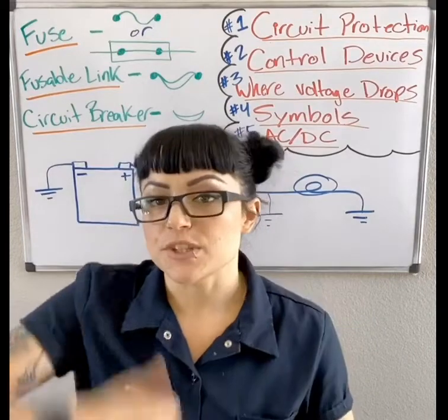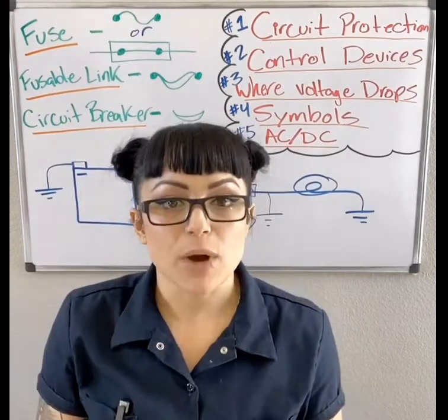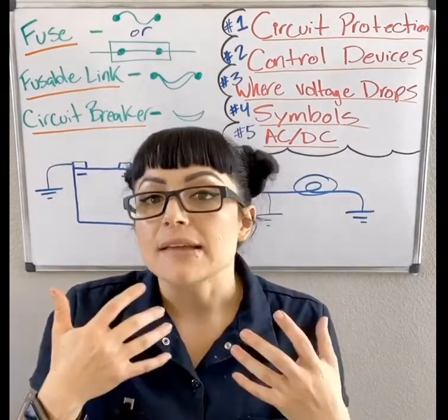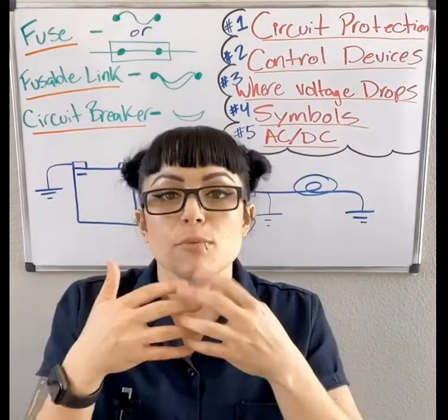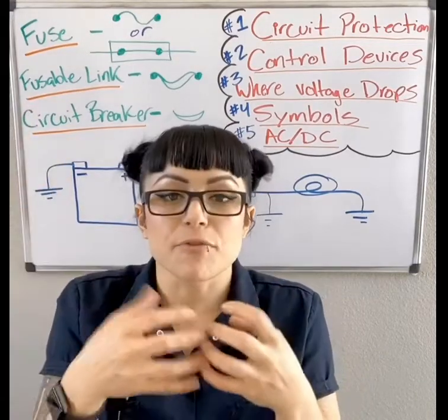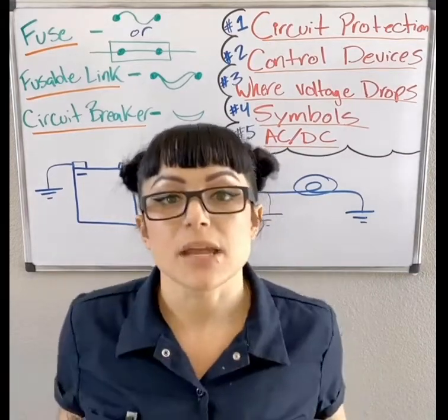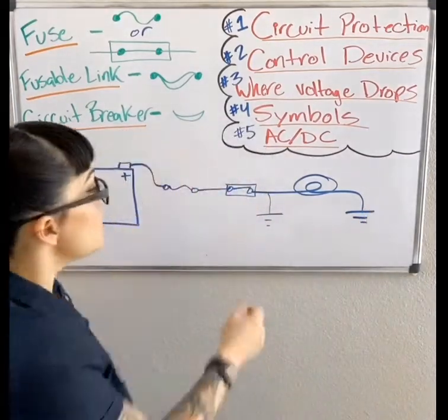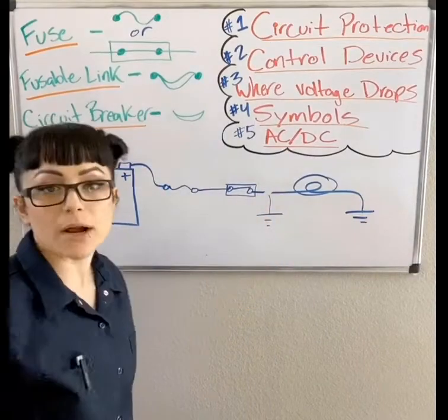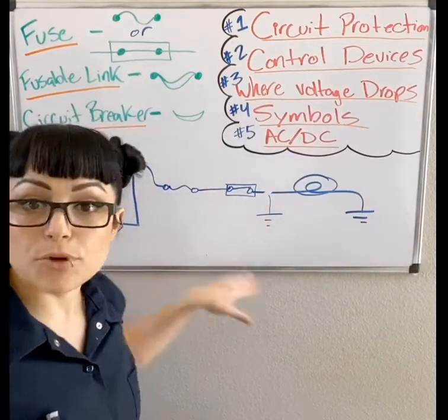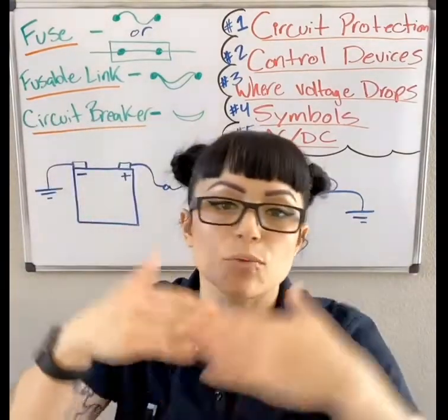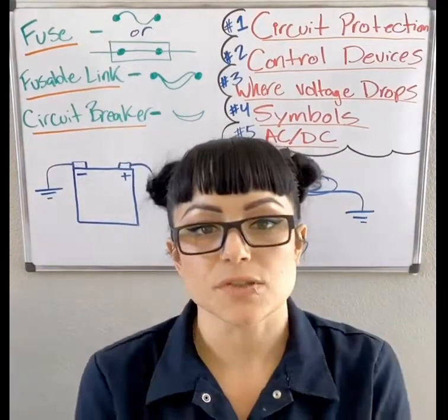The amperage flow would spike up, the thickness gauge of wire wouldn't be able to handle it, and it would heat up so much that the insulation would catch on fire, and it would get hotter and hotter until it just melted, and now there's no continuity, so it would just break somewhere. And no ground, no continuity, no flow, it would break the circuit and it would cease to get hot.